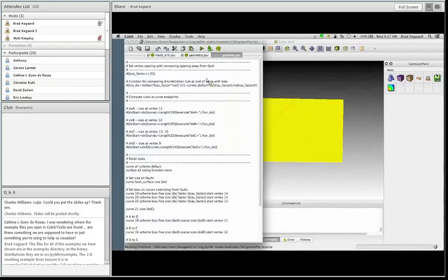In our solution, because we have isolated slip, the deformation will get smoother and smoother as we go away from the fault and where that impulse is applied. That means we can use a much coarser resolution as we increase the distance from the fault. So we're going to set a bias factor of 5%, so a bias factor of 1.05.